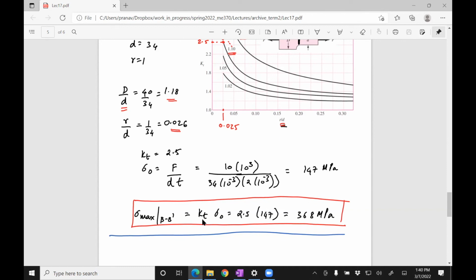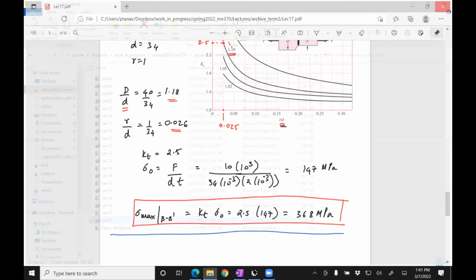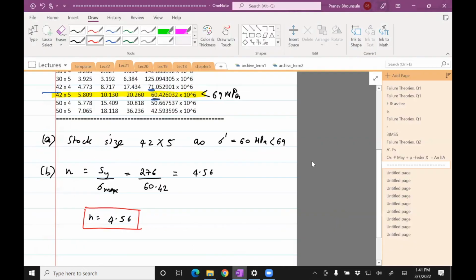If that part is very critical, when you design things, if there's redundancy, with parallel members, and if one breaks and others can take the load, then you can be a little less conservative. But if everything stands on one pillar, like in a bridge, and that pillar breaks, the whole bridge or part of it collapses, then you clearly want a very high factor of safety, because it's like a series system where if one thing breaks, the whole thing comes down. That's another reason to have a high factor of safety, which conflicts with your metric of being light.